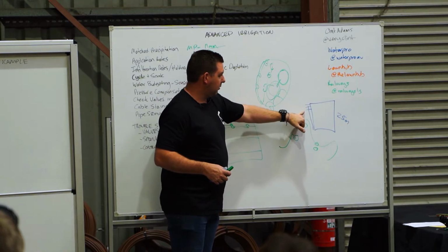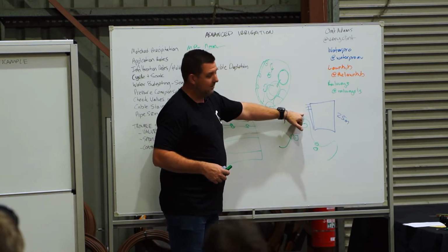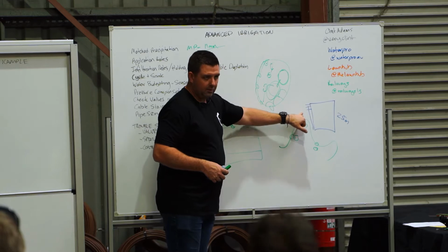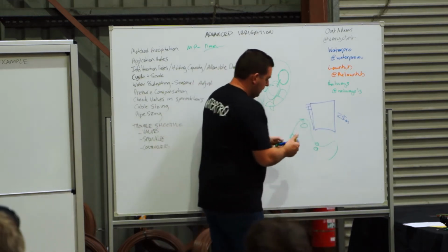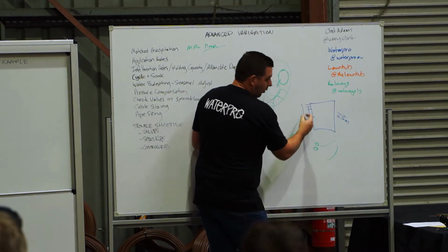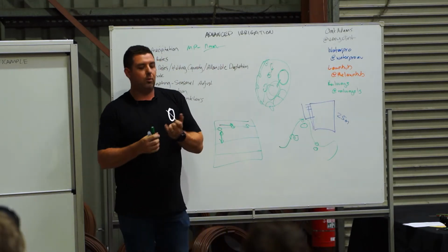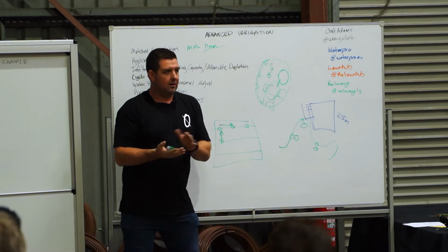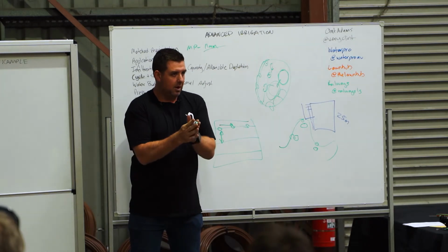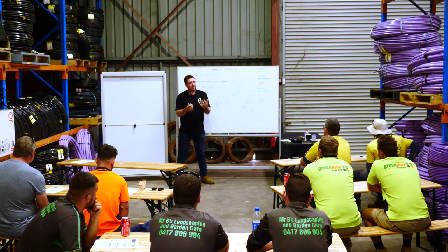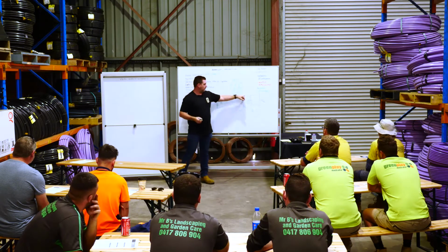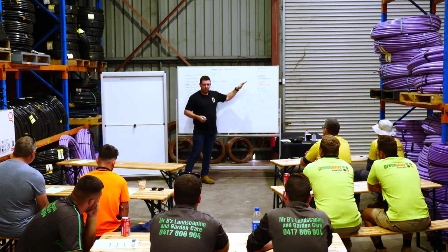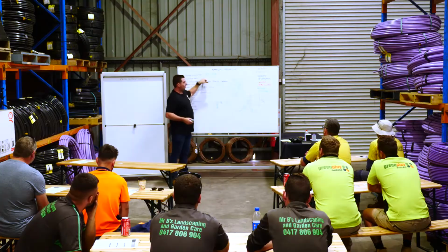The idea is that we want to let that deplete to a certain level, ideally into that 1/3 down or 1/2 down, and then re-water. So you'd let that drop by, say, 10 mil. This data is all available, and this is what smart controllers do. You have your ET that you've used each day, and it might be 2, 2, 2, and then after 4 days you've lost 8 mil. Then you want to reapply that 8 mil.